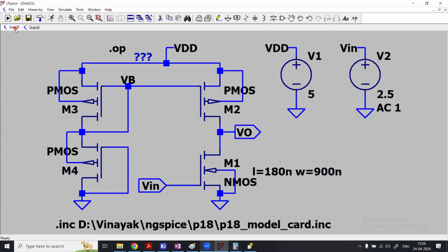So coming back to our circuit here, I've got M1, M2, M3, and M4. Now, once I put them together, like I said, M3 and M2 are acting as a PMOS current mirror together. So the current in M3 is mirrored into M2. That's how it works. Depending on the W by L ratio, we can choose the magnitude of the current that will be mirrored in M2, right?